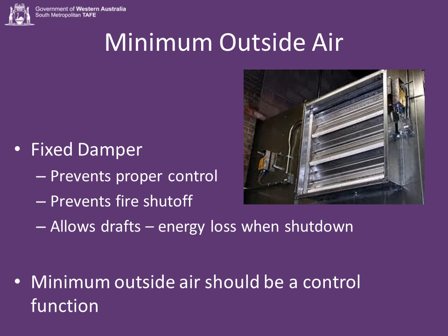The reason we used to do it, of course, was because in the days of pneumatic control systems we only had one output to all three of the dampers. But now we have separate outputs. We have a computerized control system. There is absolutely no justification for doing this absolutely heinous act. We should have a separate output and control the dampers appropriately.